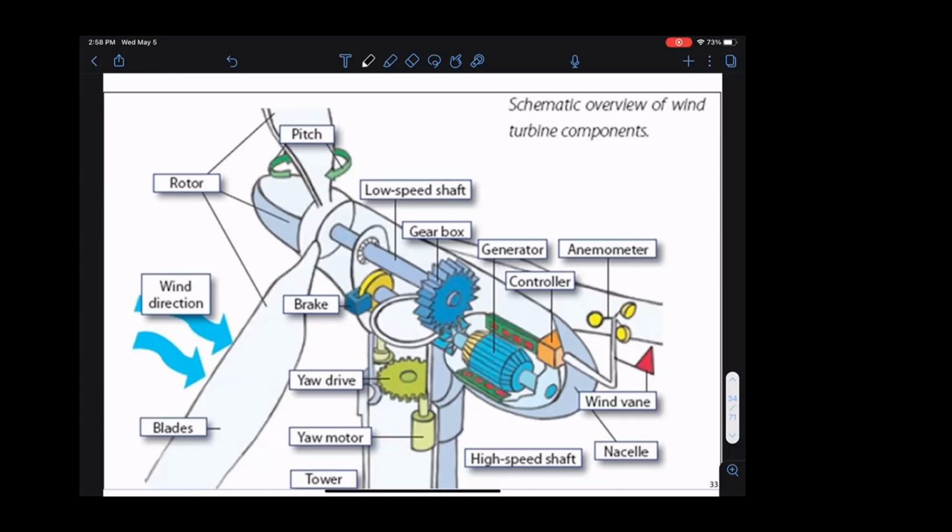So it's quite an intricate engineering problem, how you deal with wind turbines. And depending on how you engineer this, it makes a big difference in how efficient your turbine is. Nowadays, a good turbine and a bad turbine is really not about the material or things like that. One, can you build it cheaply? Two, do you have advanced controls on it? How good are your control loops around the turbine?